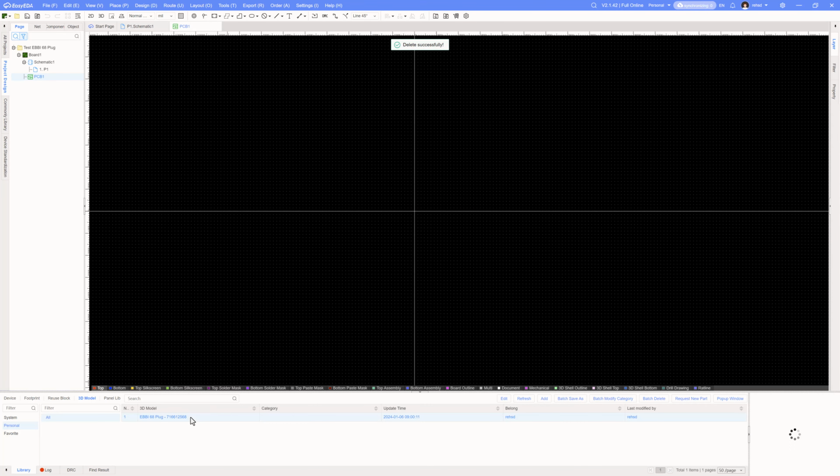One thing I do notice right away with this version, the Pro version, though, is I can directly pull in those step files, and it looks like it's rendering nicely. In the standard version, I had to convert the step file to an OBJ file, and then I would pull it into EasyEDA standard, and this would all come through as just one big black. I wasn't getting the nice visual lighting feel that you're seeing here.